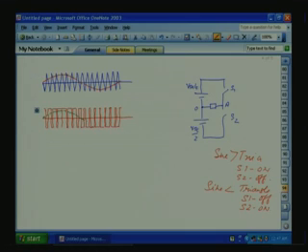The fundamental amplitude will be proportional to our VMT waveform, that is VMT, the modulating waveform. So by varying the amplitude, this fundamental can be controlled. Also, for 3-phase operation, what we do is add 3 more legs. We use the same triangle, but the sine will be 120 degree phase shifted, because we want the fundamental exactly for the 3-phase waveform.